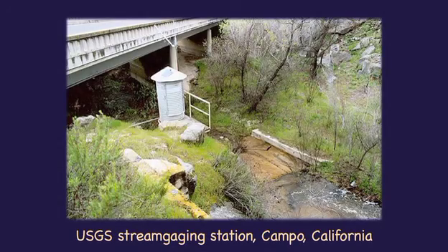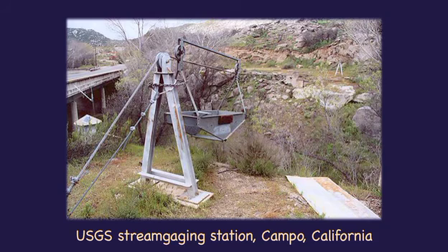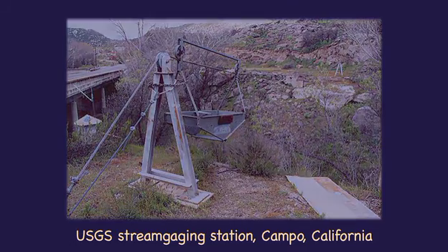The location of a stream gauging station is chosen carefully to minimize: 1. Flow non-uniformities, and 2. Shifts in stage flow rating which may be caused by changes in bottom roughness and/or erosion and sedimentation.